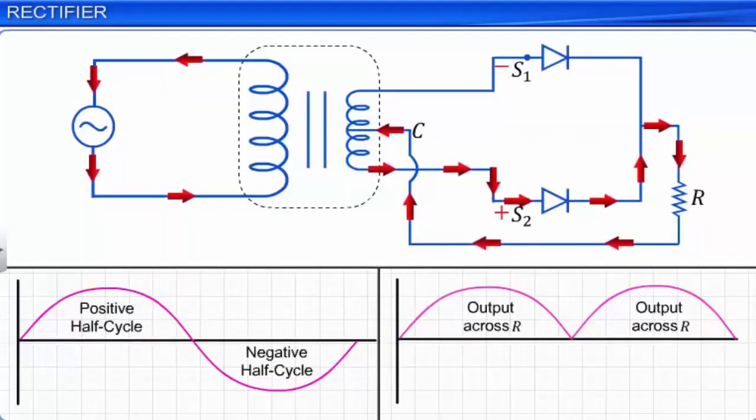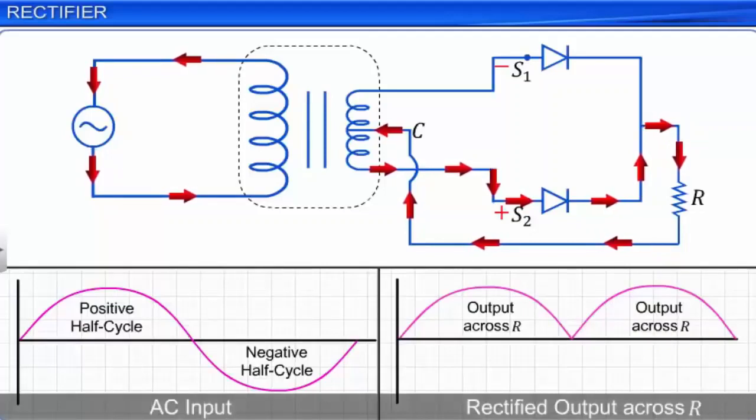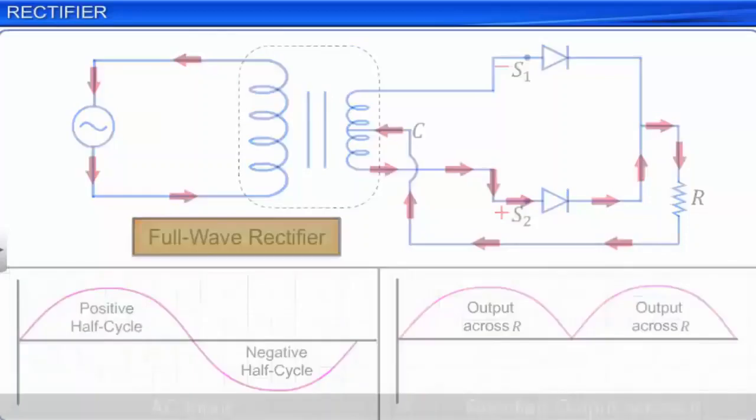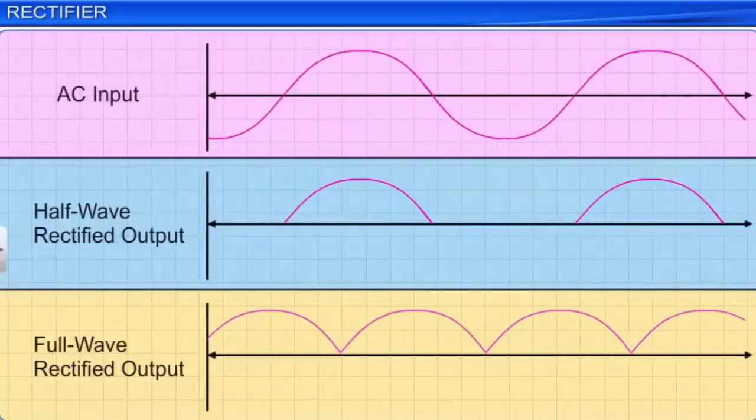A more steady output can be received from a rectifier by connecting a suitable capacitor in parallel with the load resistance. The capacitor prevents the voltage from falling sharply through the load and provides a more steady output as shown.